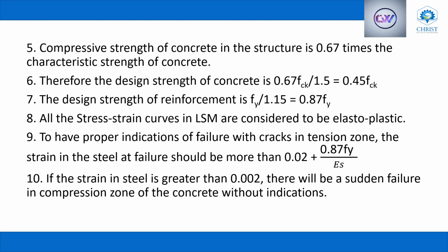The design strength of reinforcement, for steel reinforcement, we have to consider again that constant 1.15. For steel the constant is 1.15. So Fy by 1.15 is equal to 0.87 Fy. Then all the stress strain curves in limit state method are considered to be elastoplastic, the curve that we have seen already.